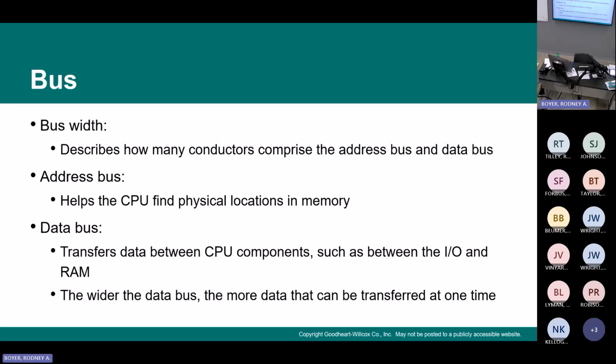Yeah, the MicroLogix family of controllers and the SLC are 16-bit controllers. You don't get into 32 until you get into the CompactLogix and above.